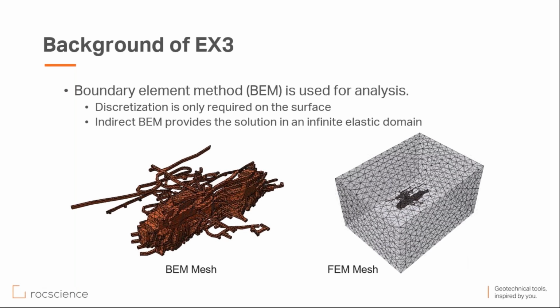For modeling in EX3, we are using the boundary element method. In this technique, only the boundaries of the geometry are discretized. So if I compare boundary element with finite element, as you can see in the picture, the boundary element mesh is only assigned to the surface. However, in finite element, the whole domain would require a 3D mesh.